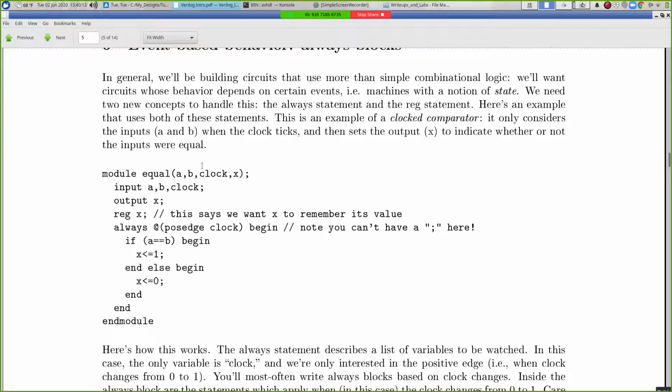And pretty much everything we do here is going to involve designs that have a clock input. Okay, really any modern circuit design that we do anymore, there's a clock input, right? Why? Because that's what drives the flip-flops to respond to the changes in their inputs. So most of the modules we make, at least one of the inputs is going to be a clock.